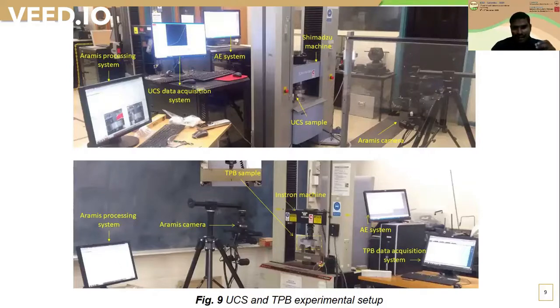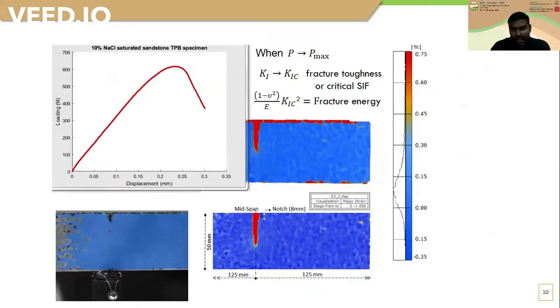Here the samples are kept saturated, and placed in the UCS and TPB test setup shown here. Then the maintained strain rates are applied to measure the load versus displacement variables. We can see that when the load reaches the critical load, the mode 1 SIF is called the critical SIF or fracture toughness, and we can also measure the fracture energy. These are the results from the Aramis camera using the surface black and white dots, which are continuously monitored, and based on pixel analysis we can quantify the strain.